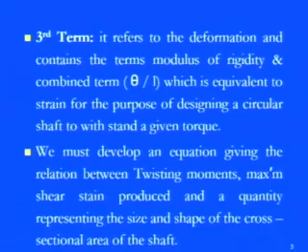So all those terms signify that T by J is exactly equal to tau by R, which is exactly equal to G theta by L. T by J gives a similar feeling: when you apply the torque, the effective area is always maximum at the extreme end. As you increase the polar moment of inertia, the effect of torque is also more. So all three terms give a similar feeling, and that's why we can say that for any kind of rotational shaft, this formula is very well valid.